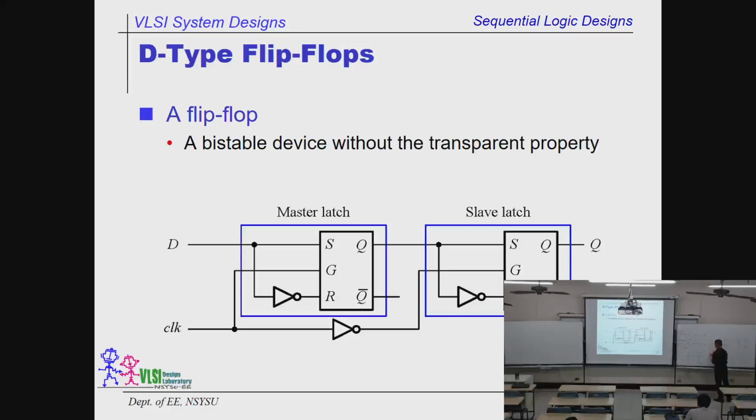And this one is called the clock. Now this is the fun part of this design. This design is a 2-stage design. This one is called the master, which is the first stage. This is D, of course. And you have a slave, which is the second stage. Okay? The only difference is that the master is enabled by the high of the clock.